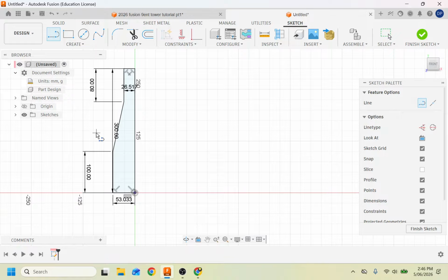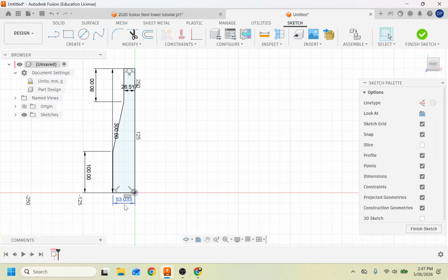One thing we do have to change here is my goal. I'm going to try to draw a line that's going to be the middle, like a spine of my pieces of balsa wood, which means I've got to offset it slightly because we know our balsa wood has a thickness. So instead of that number just being this number over here, we want to get this number and say plus 5 to make it slightly larger. And we want this number to be minus 5. There you go. And that's the shape we want our tower to follow.